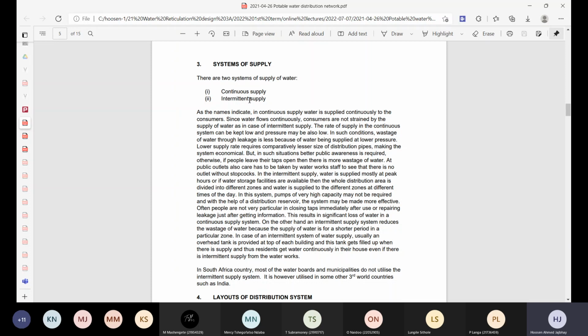When the water supply stops, the pipes empty out, and it then means you can get seepage where there are weak joints or cracks in the pipeline. You then get seepage of contaminated water into the system. So you also have a contaminated water supply system, and you can get contaminants from nearby sewage systems or stormwater systems or industrial systems where there's chemical pollution and things like that. The water supply would then become contaminated. So there are lots of issues with intermittent supply systems.